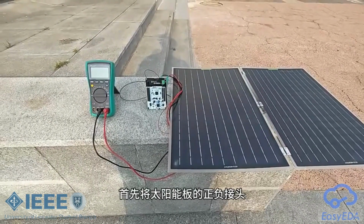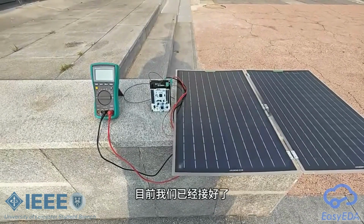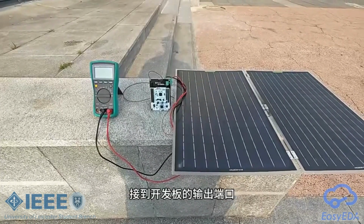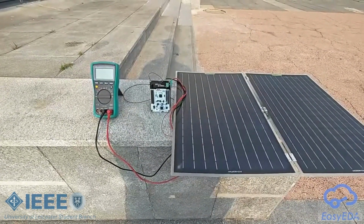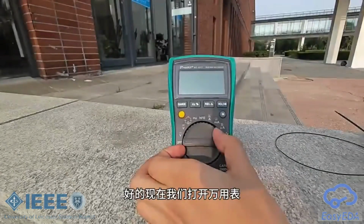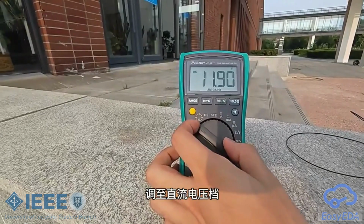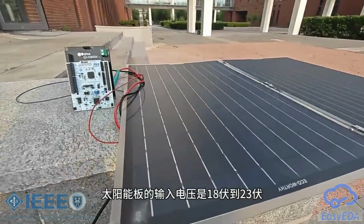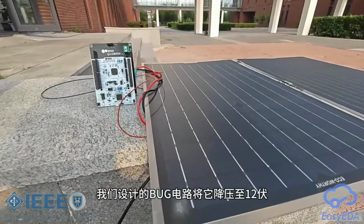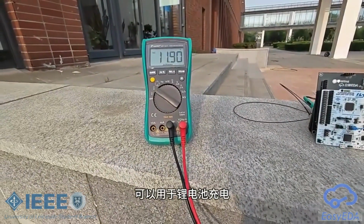So firstly, connect the positive and negative connectors of the solar panel to the power input. The second step is to connect the multimeter to the output terminal. And all the lines are connected already. Now we open the multimeter and adjust to DC voltage mode. The input voltage of the solar panel is 18 volts to 23 volts. And the buck chopper steps it down to 12 volts, which can charge lithium batteries.